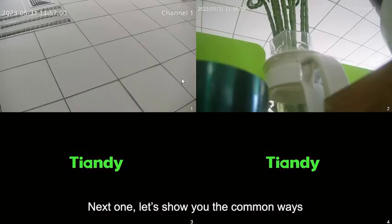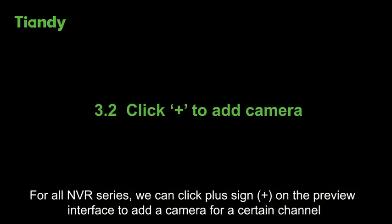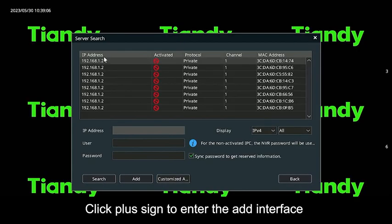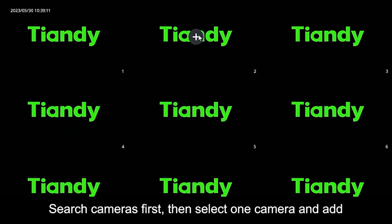Next one, let's show the common ways. For our NVR series, we can click plus sign on the preview interface to add a camera for a certain channel. Click plus sign to enter the add interface. Search cameras first, then select one camera and add.